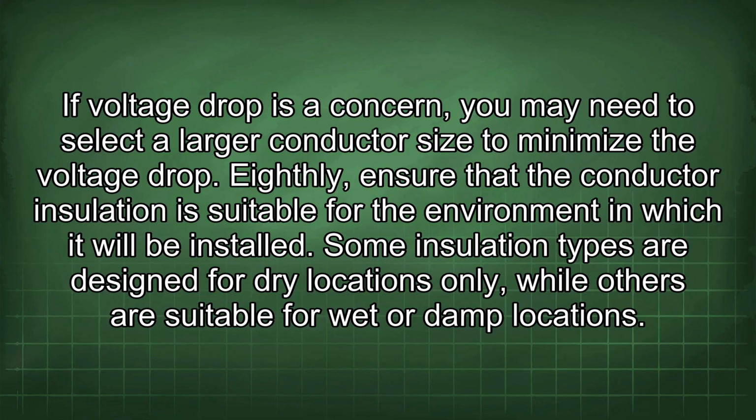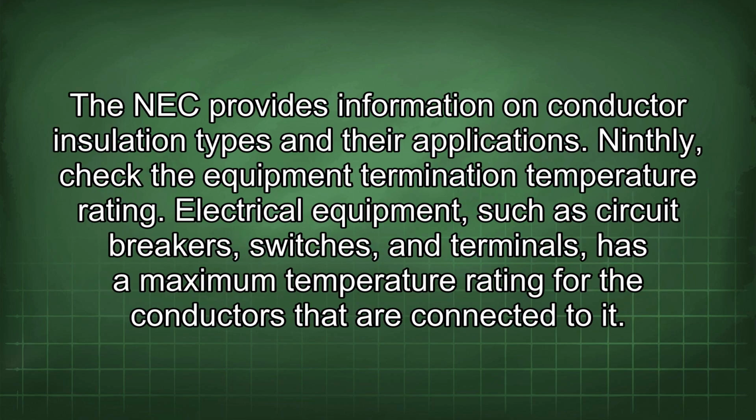Eighthly, ensure that the conductor insulation is suitable for the environment in which it will be installed. Some insulation types are designed for dry locations only, while others are suitable for wet or damp locations. The NEC provides information on conductor insulation types and their applications.